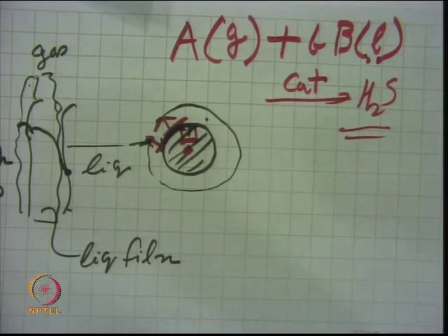It is a very complex mechanism if you look at a trickle bed reactor, gas liquid solid reaction, basically the gas liquid reaction in the presence of a solid. An alternative can be a slurry bubble column reactor, but it behaves like a CSTR, as I said earlier. So, conversion will be low, but the mixing or the mass transfer resistances are minimized when you have a slurry bubble column reactor. So, a substitute for this trickle bed reactor can be a slurry bubble column reactor.